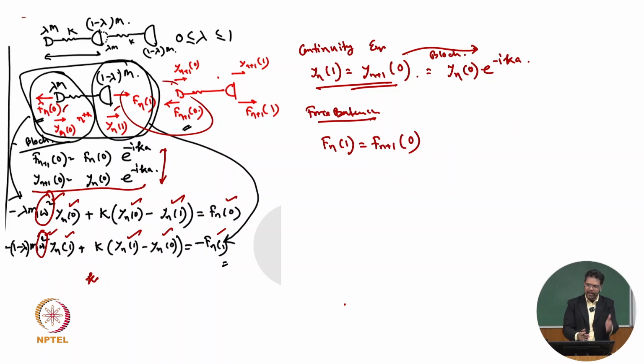So at that junction, once we cut it, they should always oppose each other. Important point: once we cut, as this is the same node, displacement should be the same for both, but force will be opposing each other because it is cut. If you cut, shear force will also oppose, bending moment will also oppose, axial force will also oppose. Agreed, all of you? That's why these force directions are opposing.